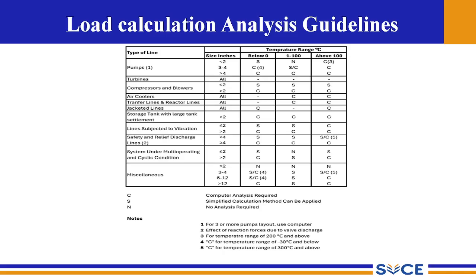Same holds good for the 6 to 12-inch lines, and greater than 12-inch lines below 0 degrees, we have to go for computer based analysis. 1 to 100, we go for standard simplified calculation methods, and above 100 degrees, we have to go for computerized calculation methods.